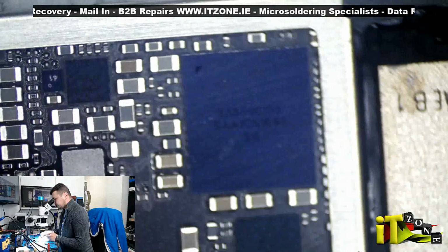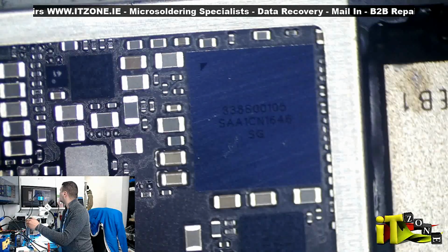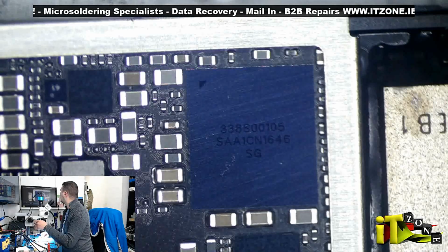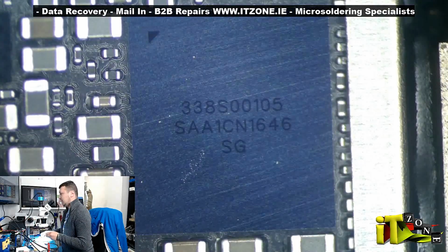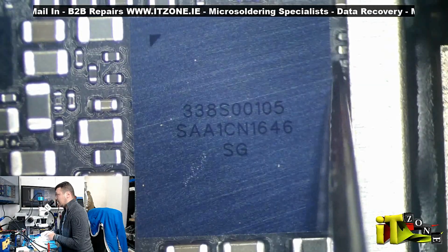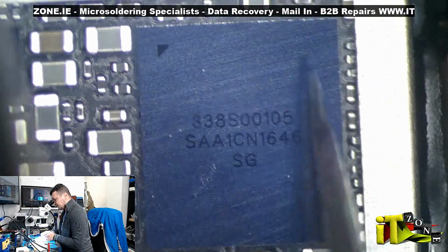So this is the IC. Let me just get this focused. I need more light. Yeah. So basically this is the IC here. The second resistor on the top right, which is this one here, which is R1103, is the resistor for master clock. So that's where we have to run the jumper from here.